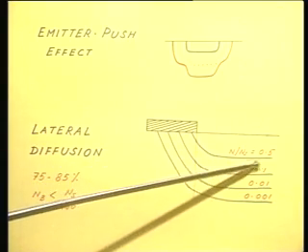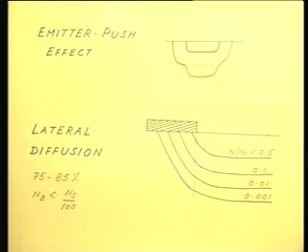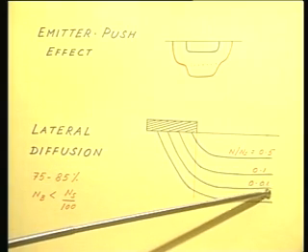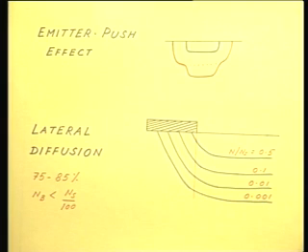This contour is for N by Ns equal to 0.5, that is where it has fallen to half the surface doping concentration. Similarly, in this case this has fallen to 1/10 of the surface doping concentration, 1/100th of the surface doping concentration and 1/1000th of the surface doping concentration.